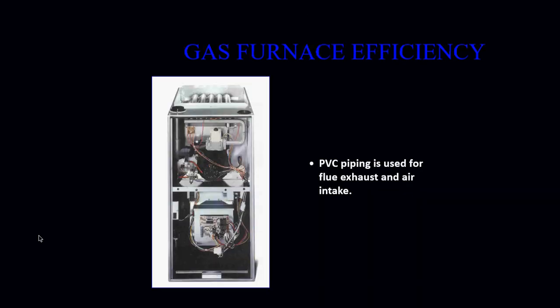Your high efficiency furnaces can also be run with PVC piping for their flue gas. We no longer need to have metal because the flue gas temperature is so low. We're only talking maybe 100 degrees, if not lower in some cases, depending on the actual piece of equipment.